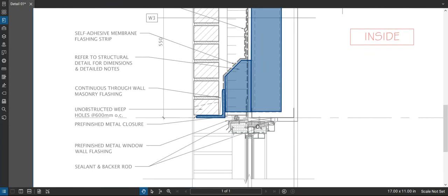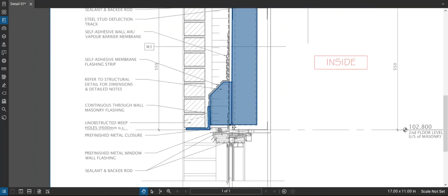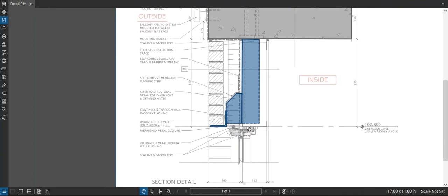The other thing I would be doing here as well is there's an opening here. I'll get to this in a second, but there's some steel stud framing in here. And this steel stud framing, the farther it hangs down, the less resistance it's going to have to wanting to bend in those directions. So framing between the drop down steel is going to give rigidity to that steel stud that's just hanging basically from the underside of the slab there.